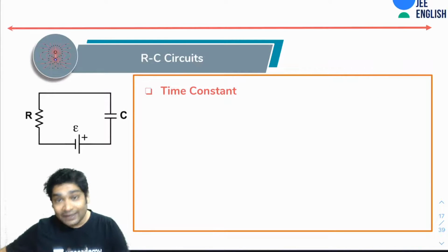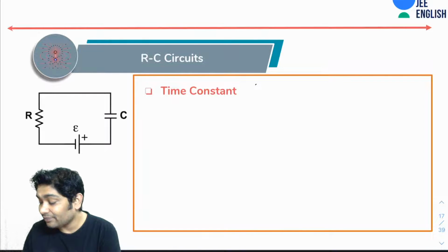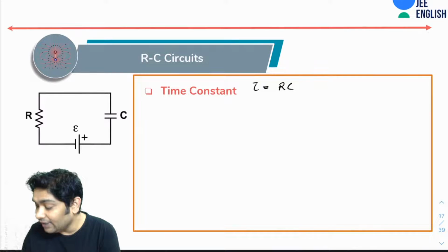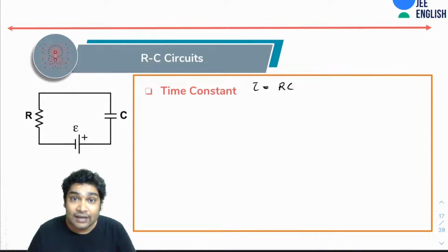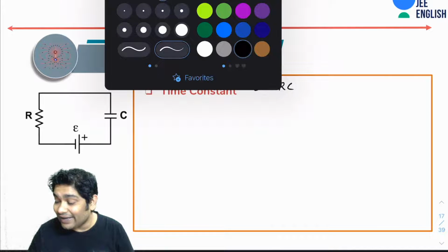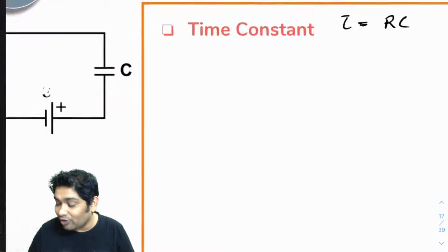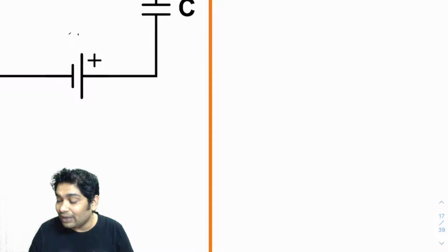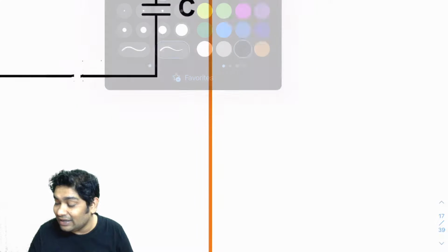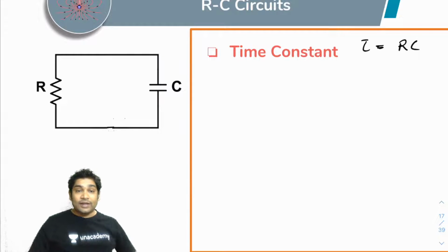Okay. So again, we also discussed a time constant here. The time constant is nothing but RC. We use the symbol tau for the time constant, and again, the time constant tau is RC. Again, why? Because as I said, the total time taken for the charged capacitor to get discharged is infinite, right? So if the total time for getting discharged is infinite, there is no point in comparing two circuits by looking at the total time required to discharge them. So which one is getting discharged faster? Which one is transferring the energy faster? To compare that, again we talk about time constants, and you realize the value of the time constant is the same while charging and discharging. So that is another interesting thing. Okay, so please remember all these.